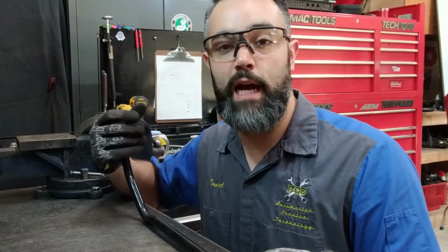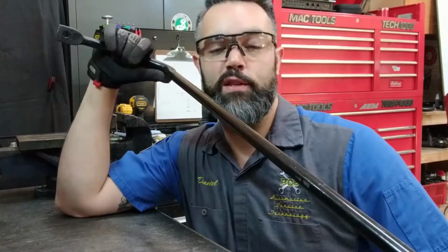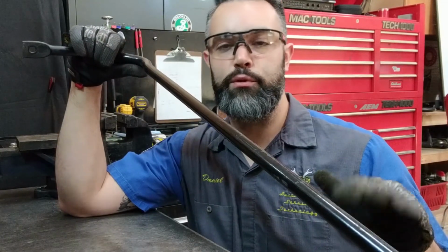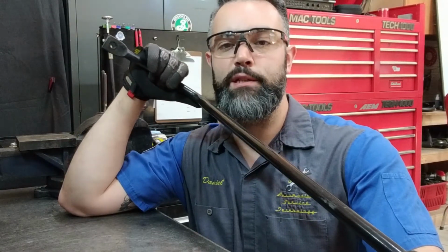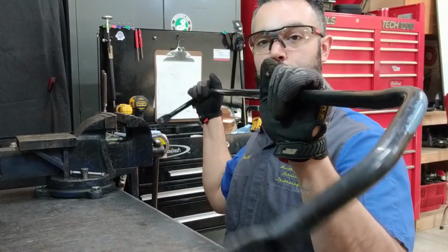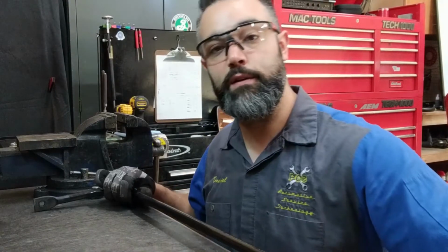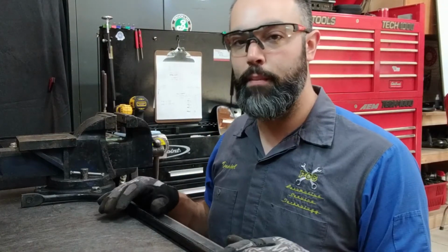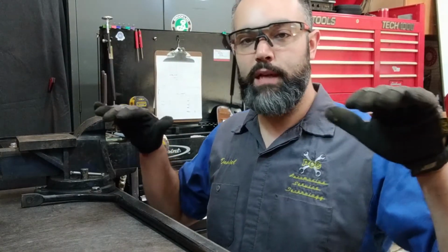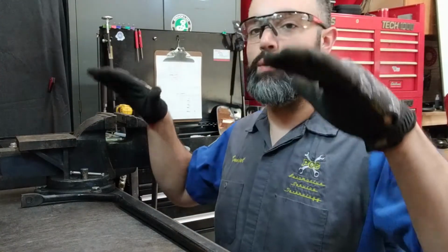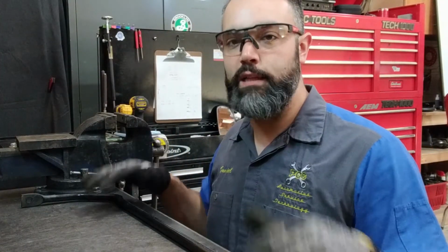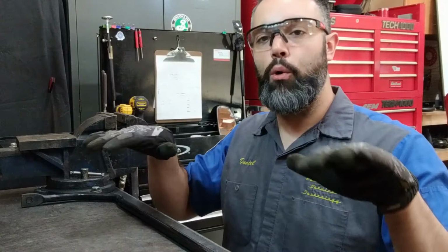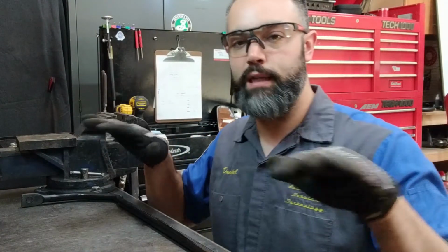Depending on the design of the chassis of the vehicle and the manufacturer's design, the sway bars need to match the rest of the suspension system in terms of how much they're going to be able to deflect and articulate with the suspension. All sway bars should be able to move without resistance as the vehicle suspension compresses and rebounds. So as a vehicle hits a bump, the stabilizer bar or the sway bar is not under tension or load when both sides are doing the same thing. The time where these are active is when each side is trying to do something different, whether that's driving over uneven surfaces or going around a turn and trying to stabilize the vehicle.